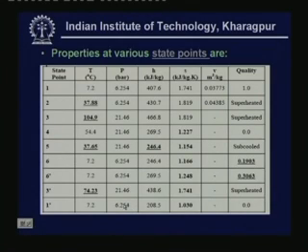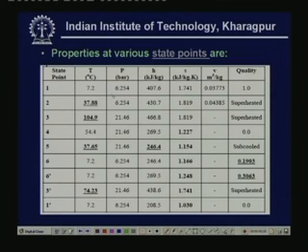So, state point 1, as I have already told you, is the exit of the evaporator, which is a dry saturated vapor at 7.2 degrees centigrade. At this point we find the saturation pressure to be 6.254 bar, and the quality, as you know, is 1. So, we give these two as the input and we find the rest of the properties. We find the enthalpy 407.6, entropy 1.741, and specific volume 0.03773.